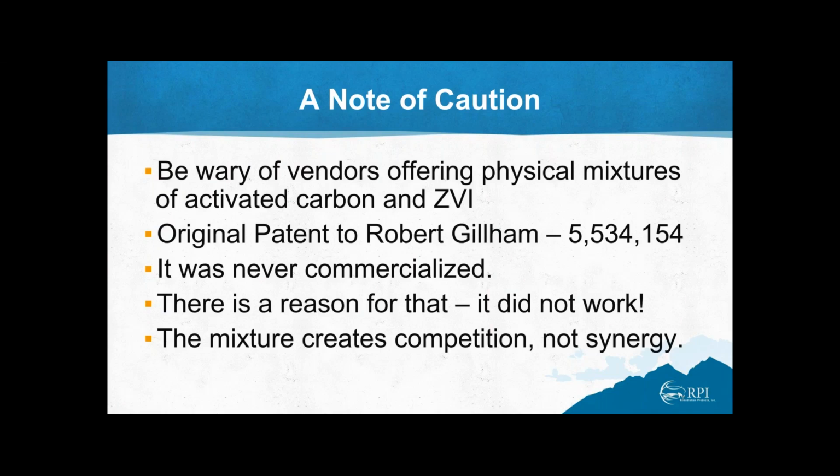Be wary of vendors offering physical mixtures of activated carbon and ZVI. The original patent, and I've given you the patent number, by Robert Gillham, was never commercialized. And there's a good reason for that. It doesn't work. It creates a competition, not a synergy.